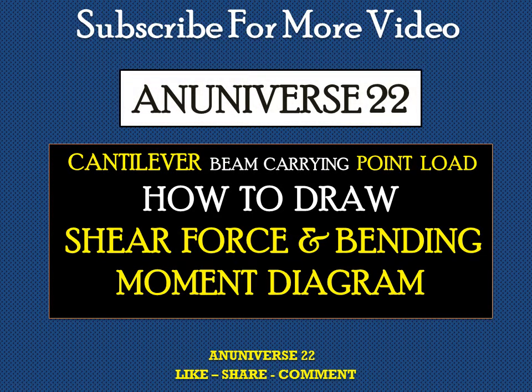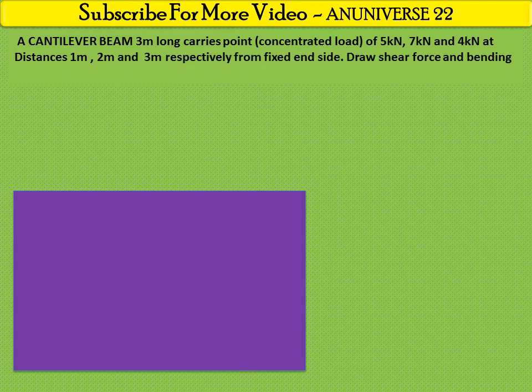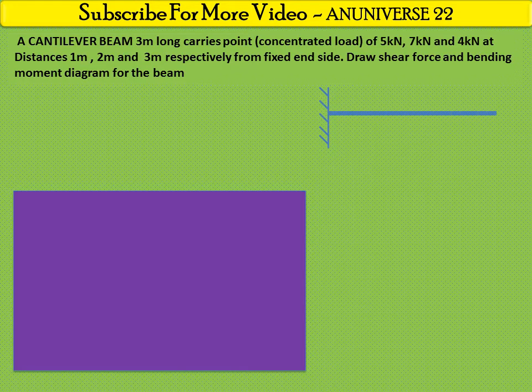Today we learn how to draw the shear force and bending moment diagram when a cantilever beam is carrying a point load or concentrated load. So we can say it is a cantilever beam 3 meters long that carries concentrated or point loads of 5 kN, 7 kN and 4 kN at distances of 1 meter, 2 meters and 3 meters respectively from the fixed end side. Draw the shear force and bending moment diagram for the beam.